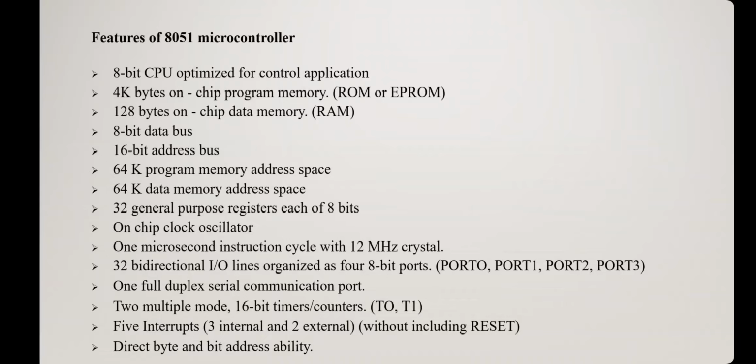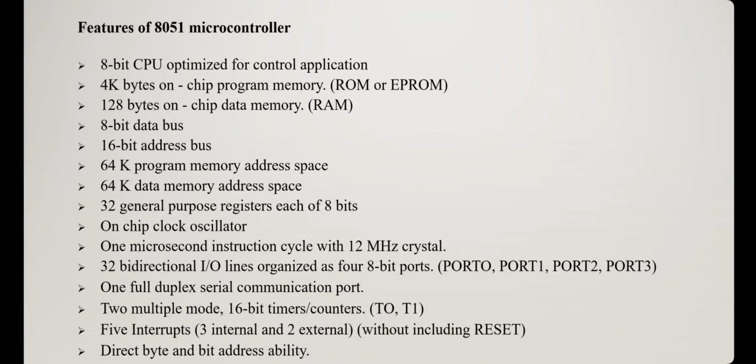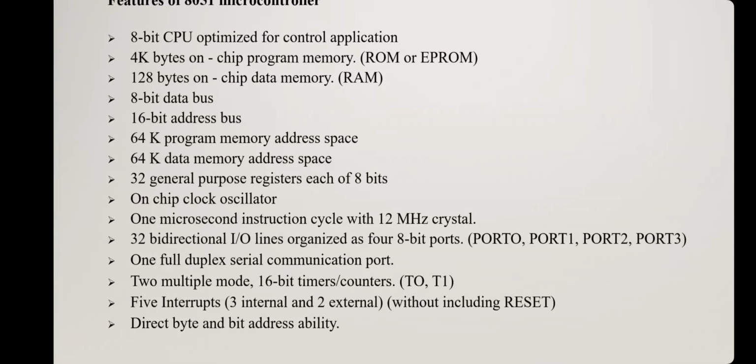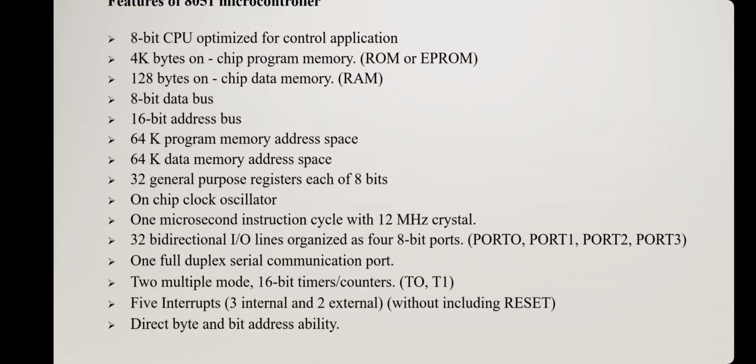Each port is an 8-bit port. Okay. It has one full duplex serial communication port and two multiple mode 16-bit timers or counters, that is T0 and T1. And it has 5 interrupts. Among these 5 interrupts, 3 are internal interrupts and 2 are external interrupts, and there is a reset pin also.